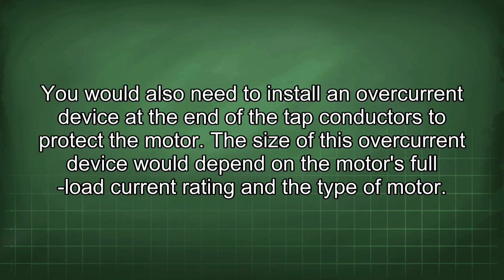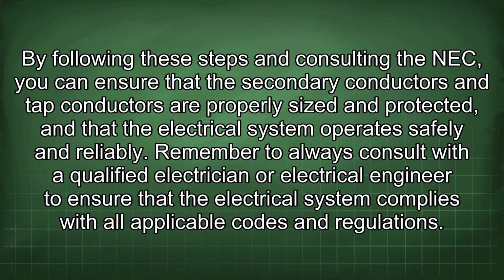You would also need to install an overcurrent device at the end of the tap conductors to protect the motor. The size of this overcurrent device would depend on the motor's full load current rating and the type of motor. By following these steps and consulting the NEC, you can ensure that the secondary conductors and tap conductors are properly sized and protected, and that the electrical system operates safely and reliably.